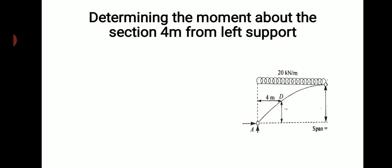Let YD be the vertical distance from the support level to the point D. So here I need to consider the moment acting at point D. I'm considering it from support A. Either you can consider it from support B also and then subtract the value asked, but here you need to consider from 4 meters from the left support itself. Therefore, I have taken A as the reference point.